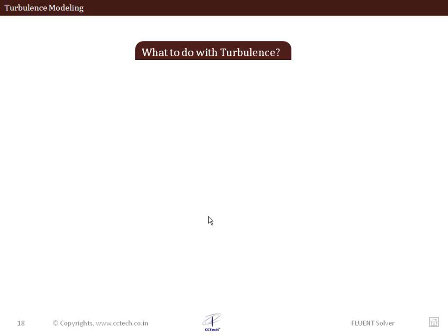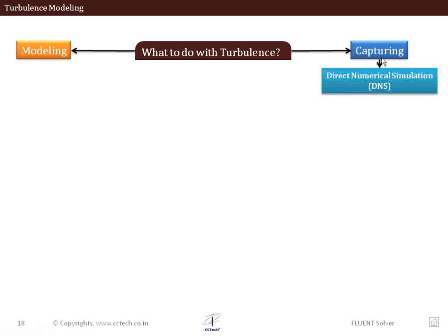And this is the question: how do we model this then? Or what to do with turbulence? So we have already seen that there is a modeling approach and there is a capturing approach. Capturing can be done by direct numerical simulations, but that's out of the question for real industrial problems.